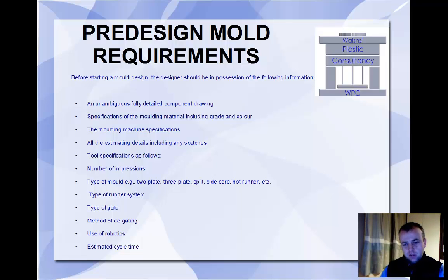Also the color, if you think you are going to have some molding issues like weld lines or sink marks. Dark colors, blue, dark greys, metallic greys, blacks are notoriously bad for showing these molding defects up. However, a lighter color, a white or a nice yellow, can mask and hide these defects.